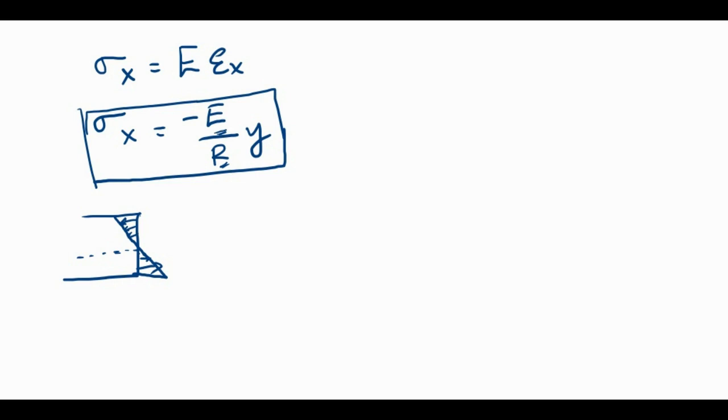Now where will the stresses be maximum? The stresses will be maximum at a point which is farthest from the neutral surface. Here, this point is the farthest point. So if it is D, instead of y we can put d, and we can calculate the maximum stress.